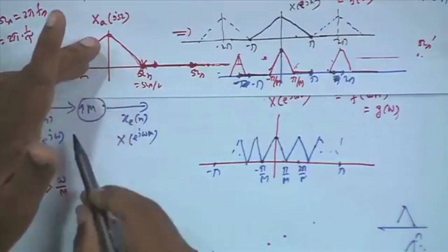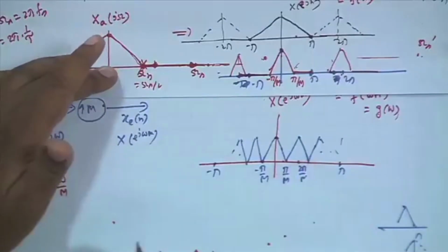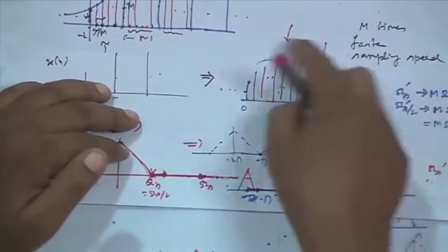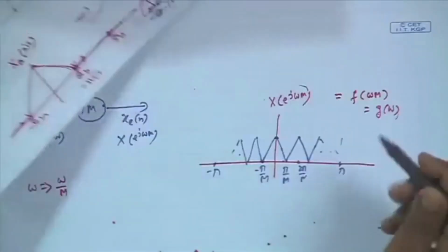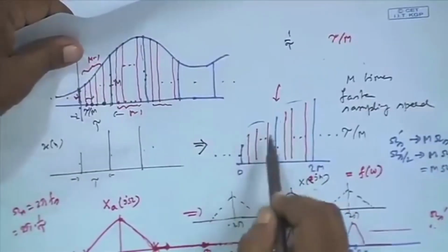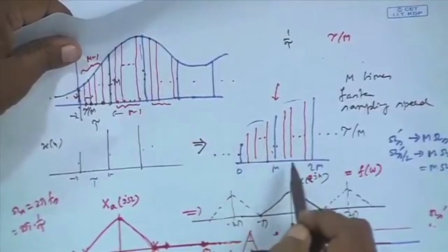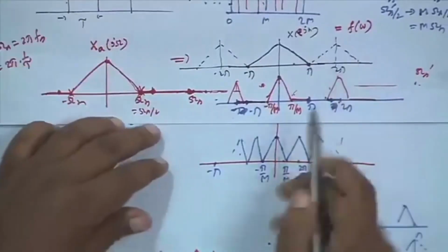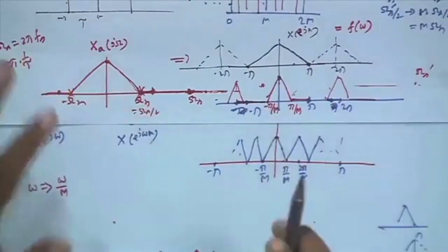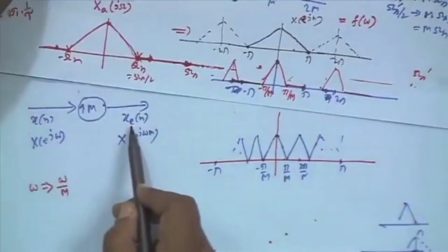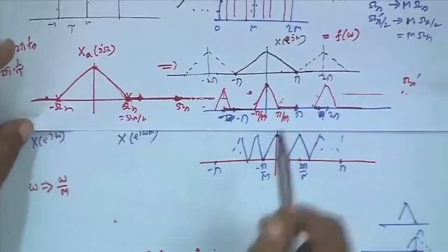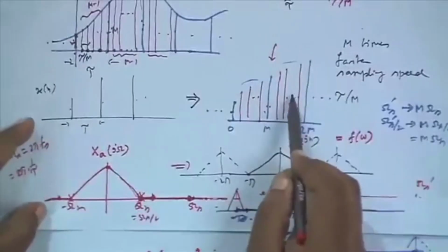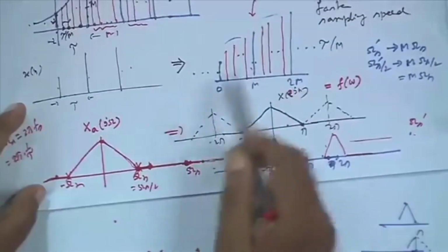But that means, if I expand, the DTFT will be this. But for the interpolated function, where I do not have zeros here, I have exact samples, what will be the DTFT of that? That we have already worked out. This is the DTFT. Then I told you, by processing x[n], I already processed x[n] and generated x_e[n]. By further processing, if I can generate another sequence whose DTFT is this, then I am done, because if this is the DTFT, then in the time domain this will be the sequence, because one DTFT corresponds to only one sequence.